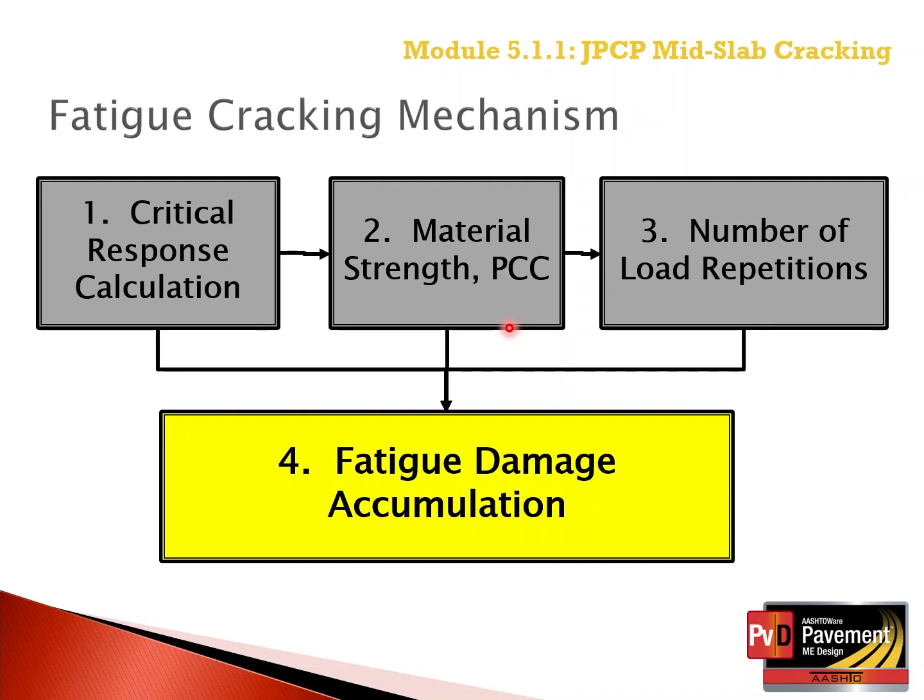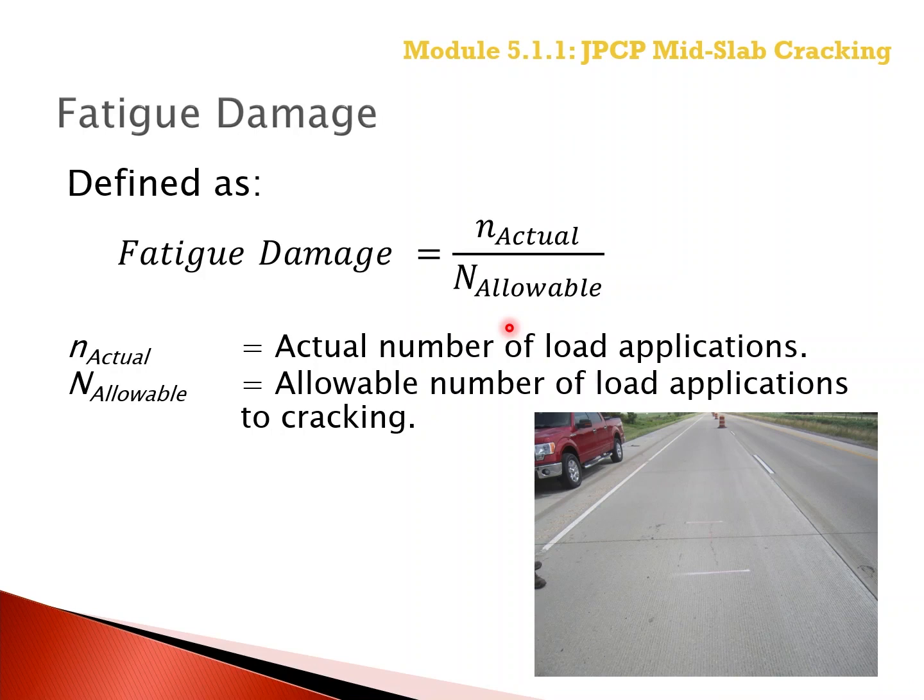The fatigue cracking mechanism includes calculating the Portland cement concrete incremental fatigue damage and summing it to demonstrate the total fatigue damage over time and within the PCC slab. This session of the module will explain and discuss the accumulation of the incremental fatigue damage in the Portland cement concrete slab. First, what does the incremental fatigue damage accumulation mean? And how is it determined?